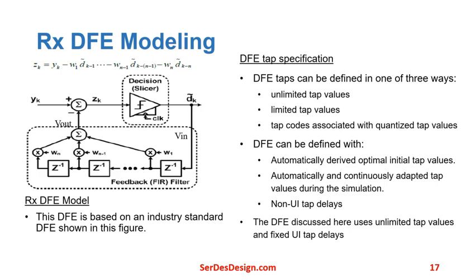The DFE model is based on an industry standard DFE architecture shown in this upper left figure. The DFE taps can be defined in different ways. The taps can be defined with unlimited values, with limited and quantized values. The DFE can be set up to automatically derive optimal initial tap values. The DFE can automatically and continuously adapt tap values during the simulation. The DFE taps can also have non-UI tap delays. The DFE discussed here uses unlimited tap values and fixed UI tap delays.